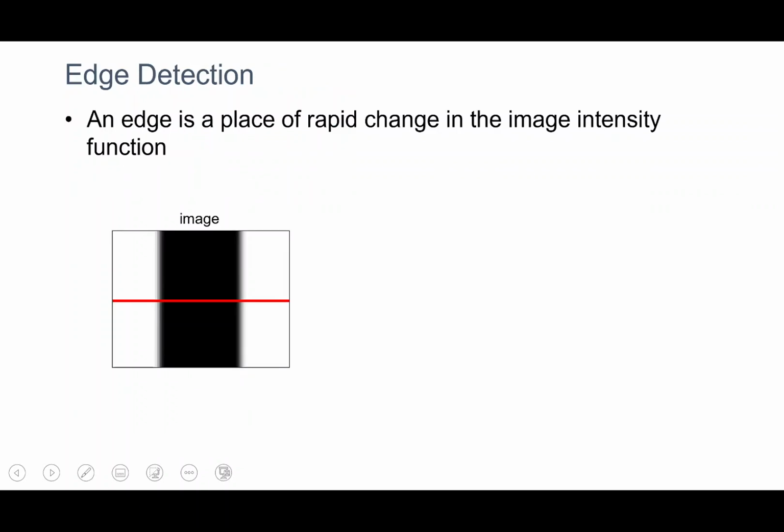So we already did the linear filtering, image blurring, and we understood the concept of separability. When you can have the 2D filter as the outer product of two 1D filters, and the bivariate Gaussian is a good example of this, which we can represent as a product of two univariate Gaussians. And then we learned about median filtering also, which is not a linear filter but an order statistic filter. Okay, so now let's look at these edges, and here you can see a noisy image,